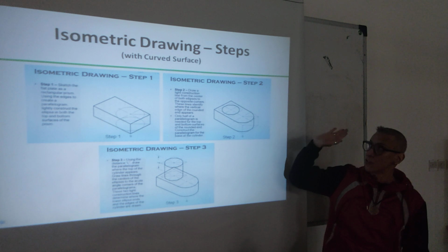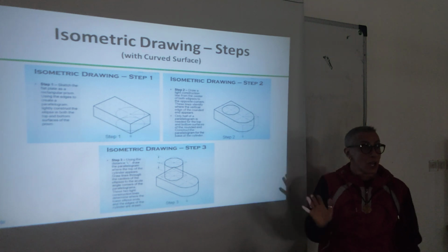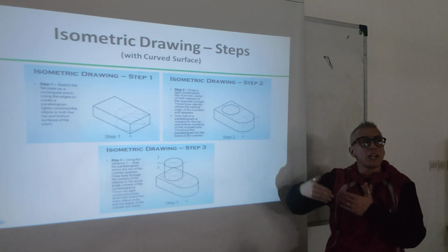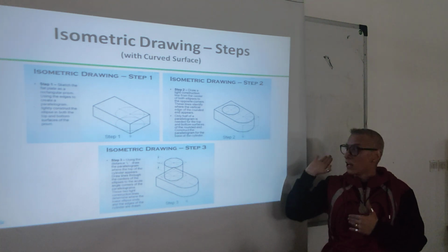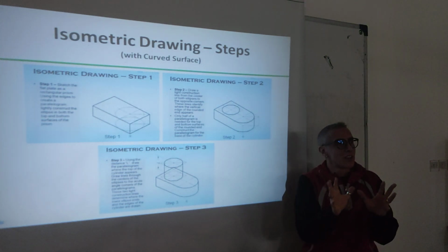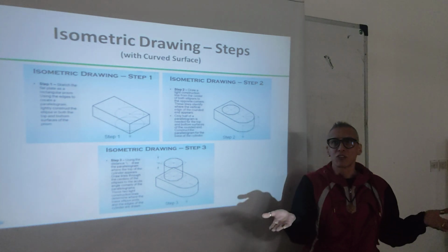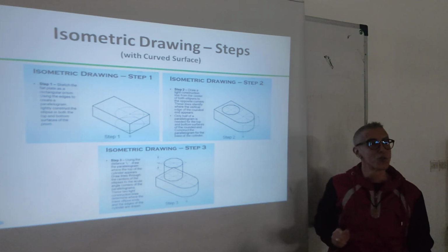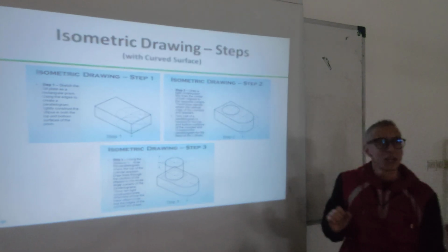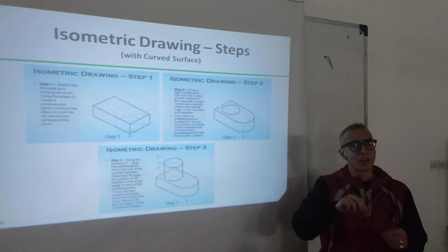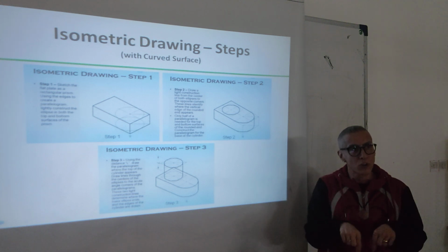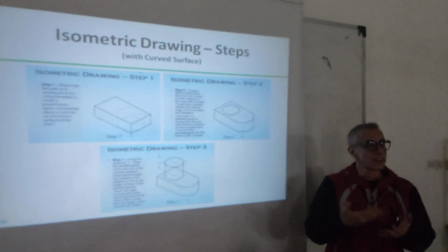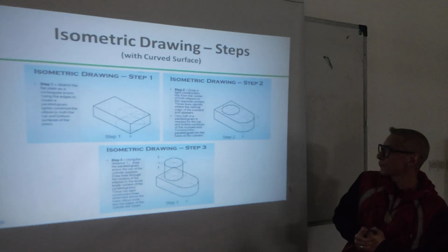This box stays. These are the construction lines. Okay? At least in this class, you don't delete anything, because I need to see how you constructed something. I don't need to see a final only object without any construction lines. I will think it's copied from someone, okay? Then I will start searching from whom it's copied. So no, all the construction lines, the details, everything, how you build it, needs to be on the drawing. But with the correct line weight, light lines, not heavy lines, okay?